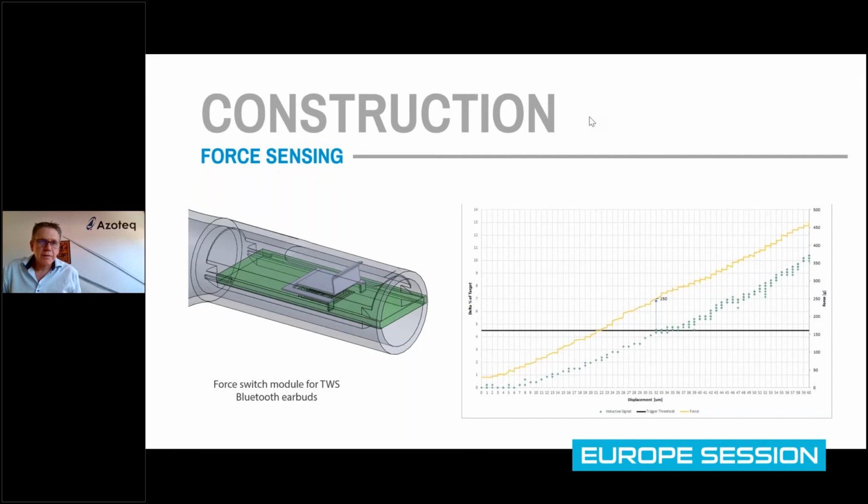And the same when you have a very high sampling frequency, the power consumption will also go up. But if you can get away with either less precision or with a lower sampling frequency, then the power consumption goes down again. So you are welcome to share a specific example or a specific application with us, and we can give you an estimate of what the power consumption would be. For sure, still appreciate your support.